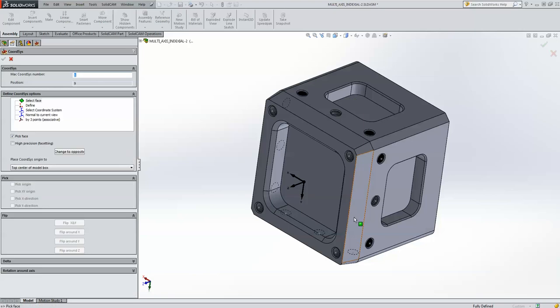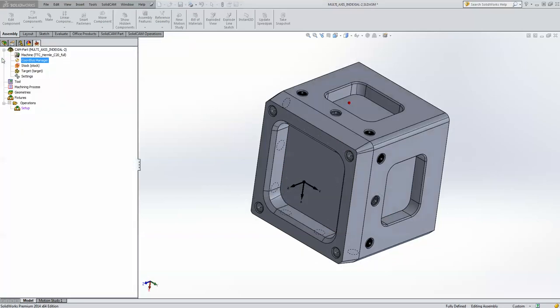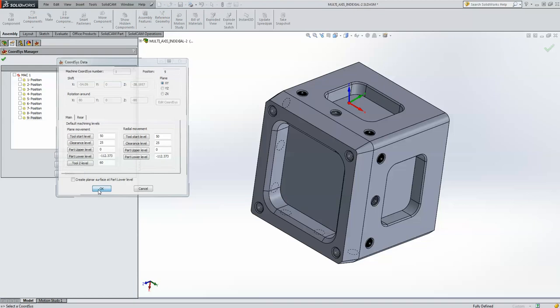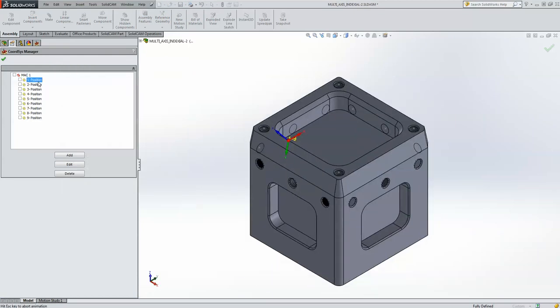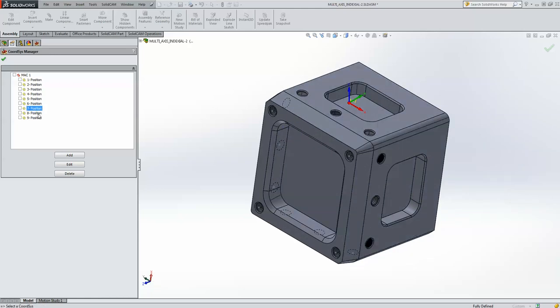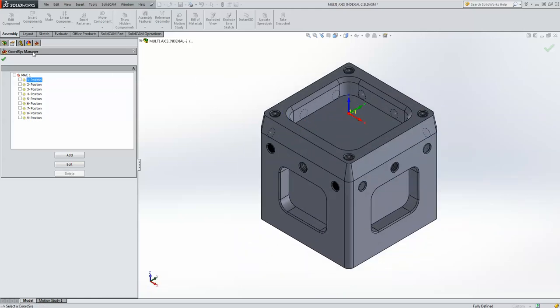on this surface over here. Again, flipping around, this time just once. And I can see my Y direction is in the proper area. So if we take a look at all the home positions that we have here, we have our very first one, second one, as it flips around the part itself, then this way, we have all our home positions exactly the way I want it.